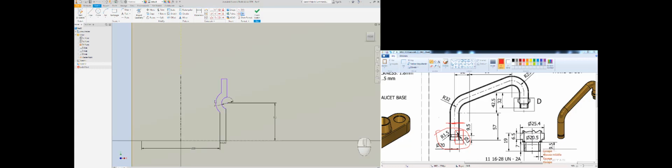And the top side, as you know, we have created this profile. It is not fixed, but I know these two lines are following each other. For this, I will use the collinear constraint to make these lines aligned. The next thing, we will have a tangent condition here at this point. You can have the midpoint of this circle on one of these lines. Make this point coincident on this line.